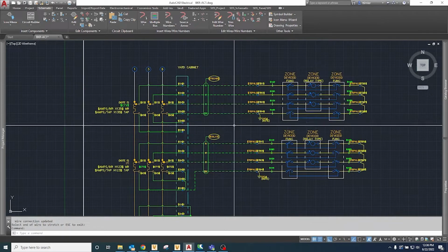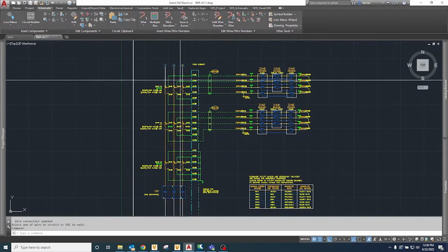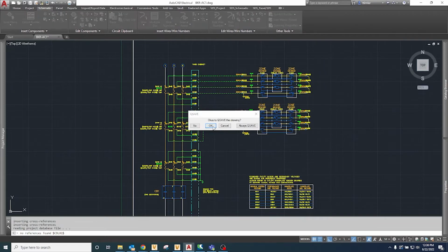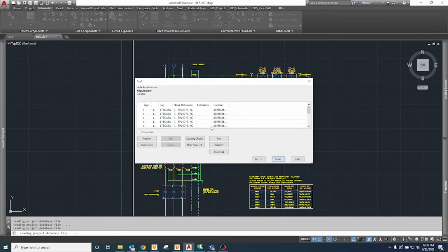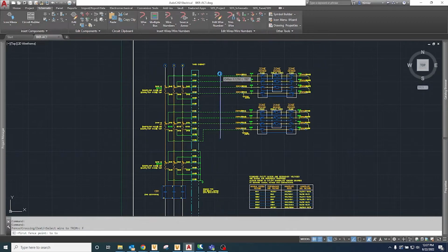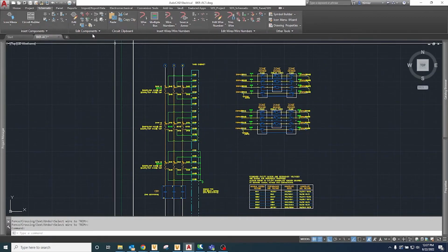Now I'll demonstrate a change in phasing that affects the cabling. I could go about trimming and redrawing each individual conductor to the corresponding inputs, or I can delete them and use Add Circuit. So I'll delete the cables. Go ahead and just freshen up. And then hit Trim Wire. Just do a fence around these wires and trim them up.